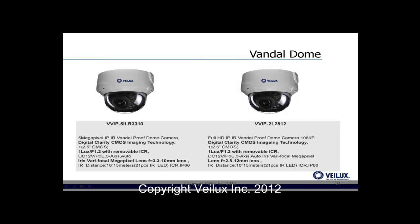The Vandal domes. The VVIP-5ILR3310. It's a 5 megapixel IP IR Vandal dome camera. Digital clarity CMOS image technology, 1 lux, 1.2 with removable IR cut filter, 12 volt DC power or PoE, 3 axis, auto iris, varifocal, megapixel lens, 3.3 to 10 lens. IR distance is 10 to 15 meters, 21 pieces IR with IP rating of 66.